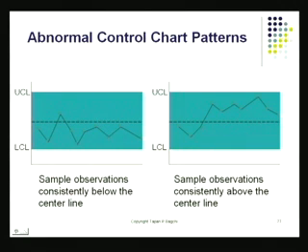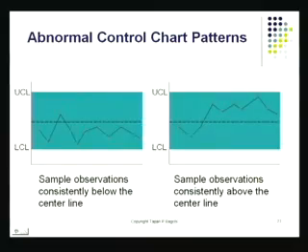Stop the process, because it may be too late if you wait for a real point to go beyond the control limit. You might have produced a lot of useless production. You may have produced a lot of widgets that have no real use. They are not going to fit properly, because the pattern has already shown that there are some unusual variations.